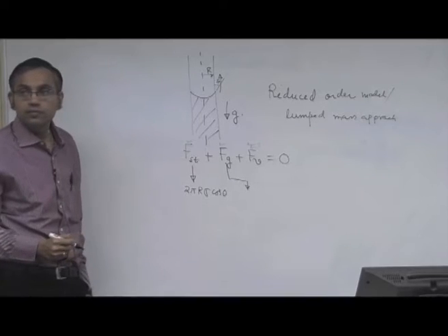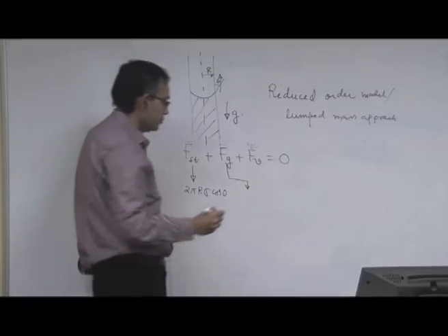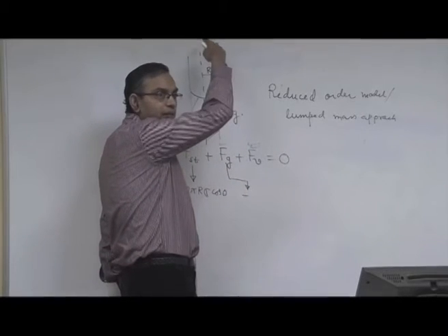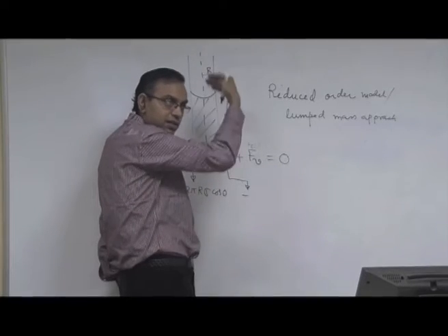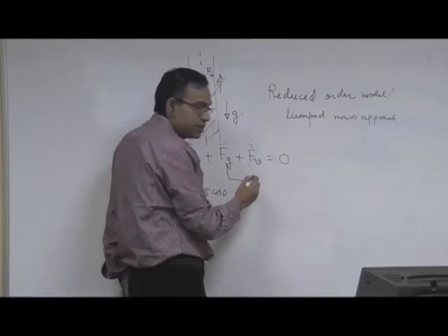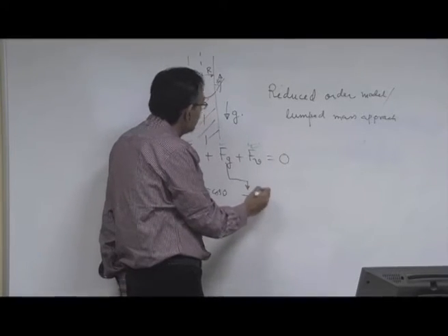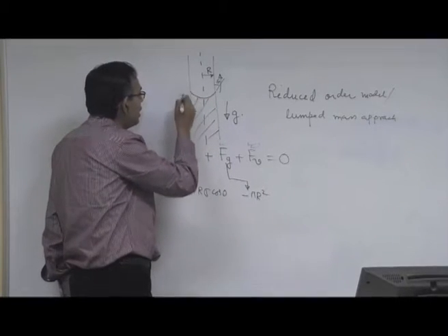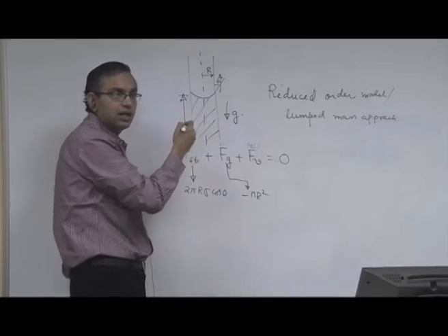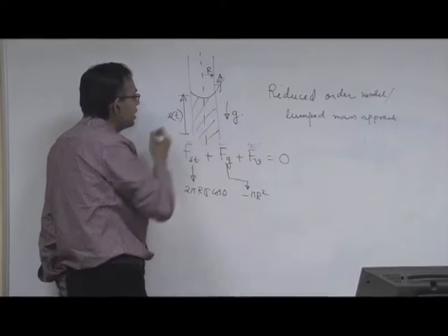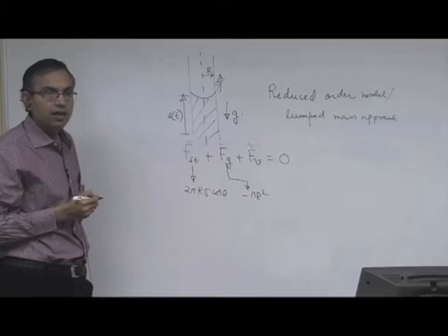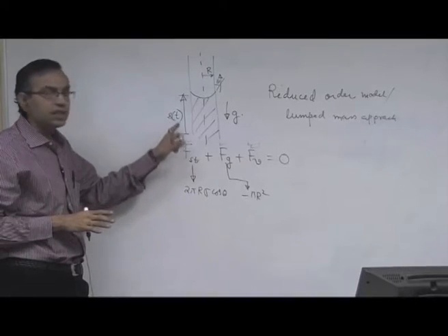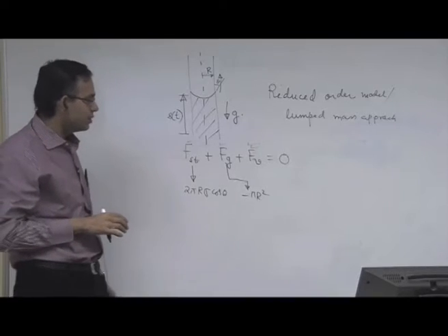Gravity force, first it is minus, because surface tension is pulling the fluid in the upward direction and gravity is resisting it, opposing it. So, minus pi r square, let us say, this is the instantaneous displacement. Let us say this is S as a function of t. The final equilibrium value of S is h, but S changes with time as the capillary front advances.